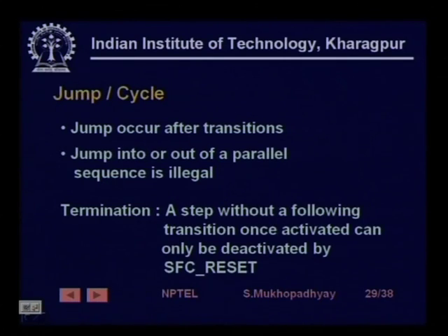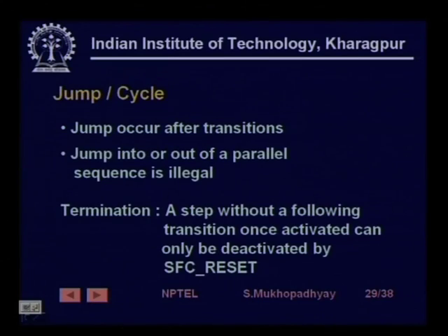Similarly, lastly you may have termination of a program. So, a step without a following transition. If you have a step out of which there is no transition, then it is a dead state, and once it is activated, it can only be deactivated by a special instruction called SFC reset.